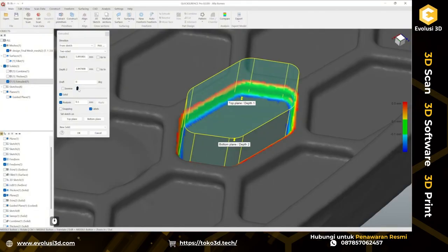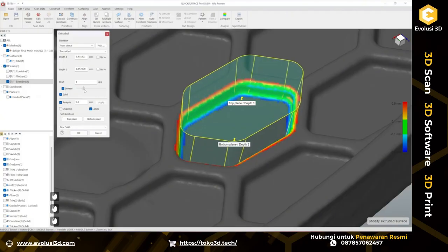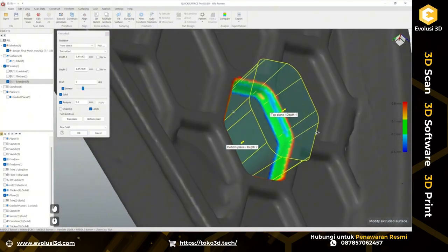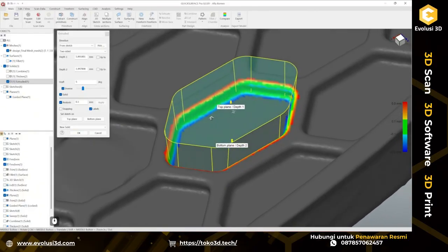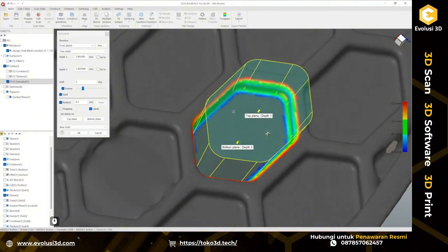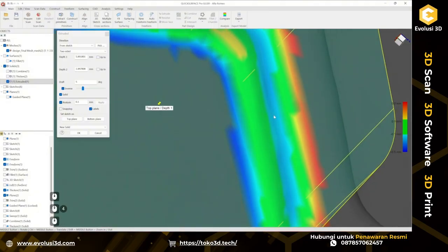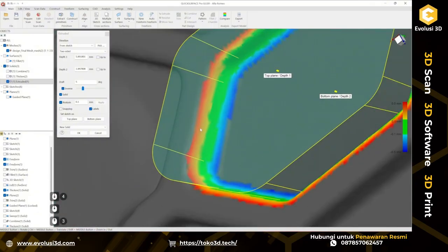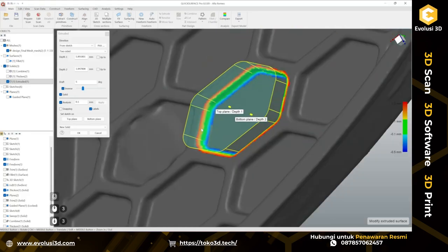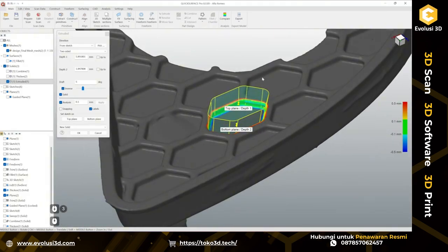If we imagine how this part was created, most likely this is some sort of injection molding, so there must be some draft in order to take this part out of the mold. And of course at this moment we can see some slight deviation in one direction and on the opposite side slightly in a different direction. So basically this extrusion should be slightly tilted.